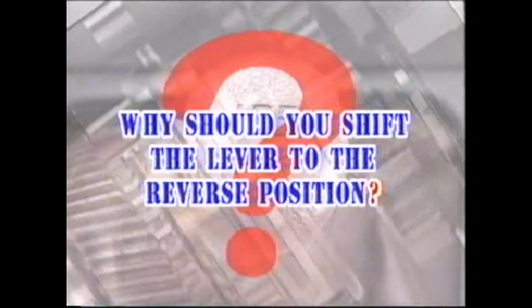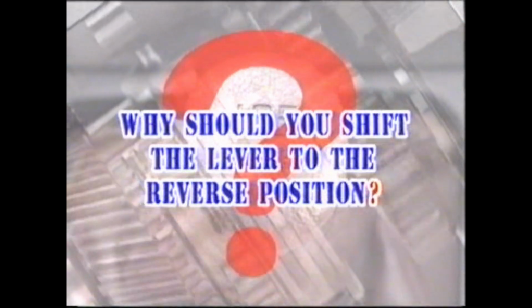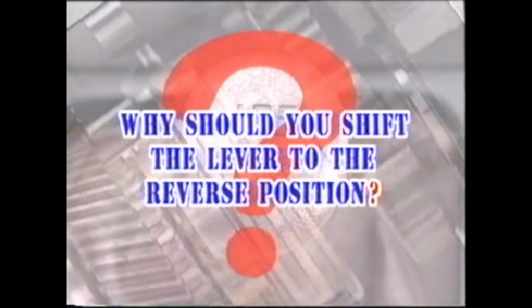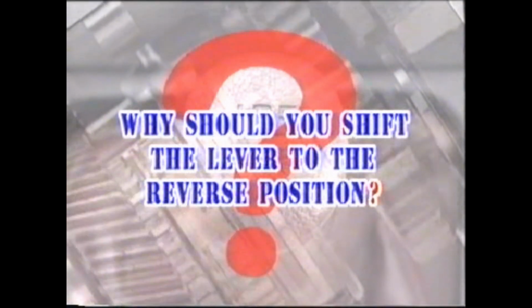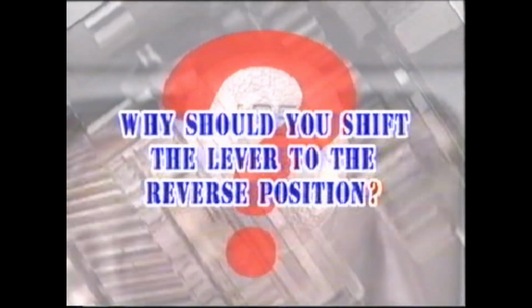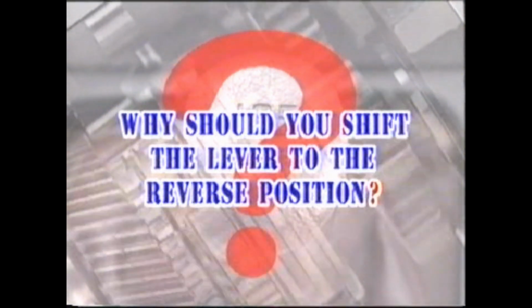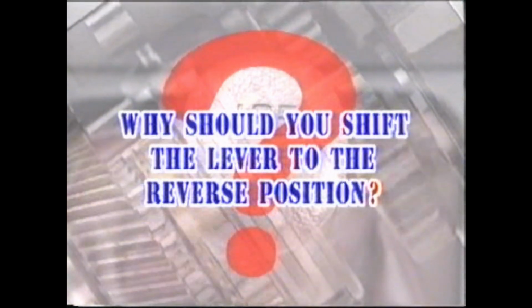Since the reverse gear does not have a synchronizing mechanism in most transmissions, the gears cannot be engaged easily or sometimes cannot be engaged at all when the clutch has a disengaging problem. So the problem can be identified more easily than by shifting into a forward gear.